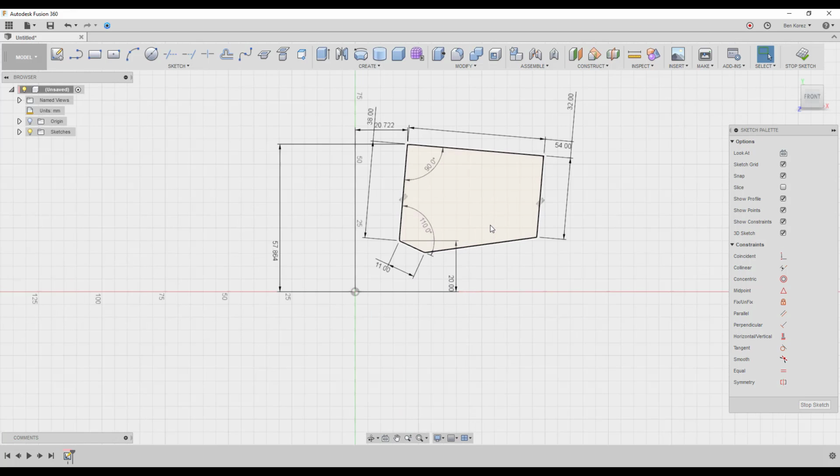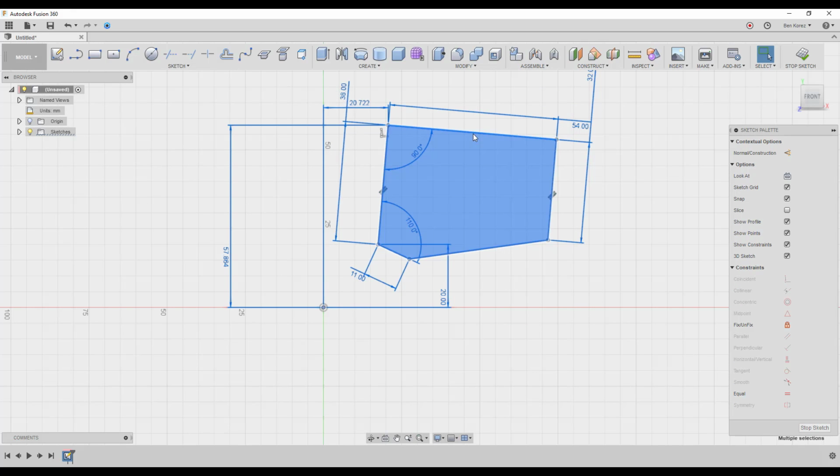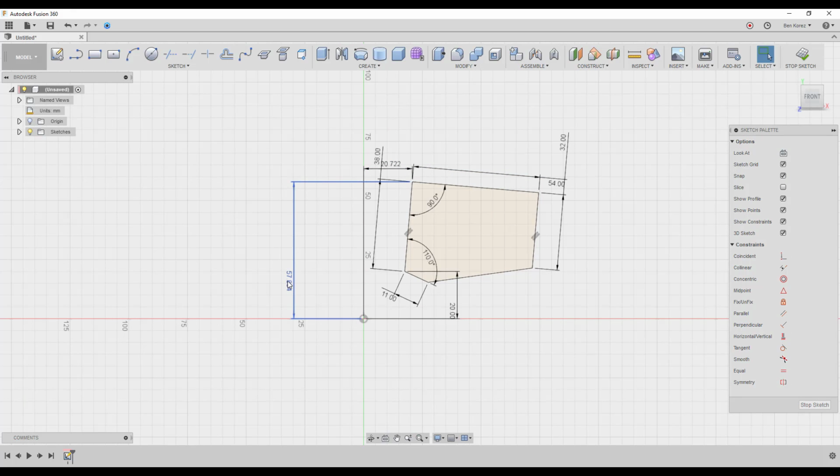How do I know? Because the color turned into black, which means even if I select everything, I cannot move it. So that's basic, it's quite simple. That's the difference between fully constrained and constrained geometry. Okay, so remember to constrain your geometries. It's very important because you can accidentally, when you're creating another sketch beside it, or changing an angle or something like that, really screw everything up.